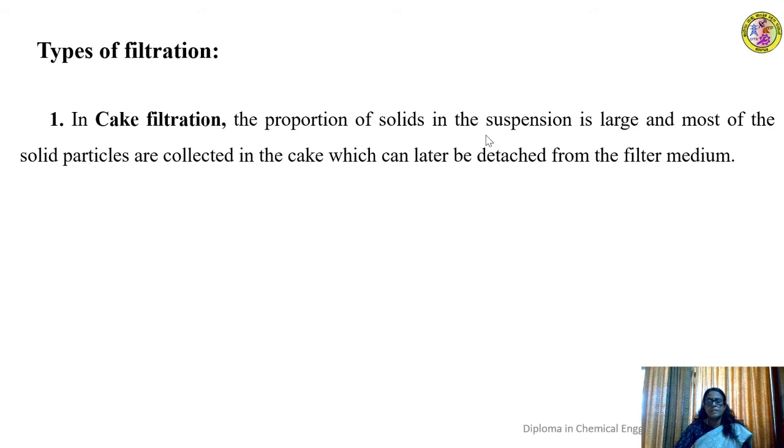The proportion of solids in the suspension is quite large, as I already told you. Most of the solid particles are collected in the cake, which can later be detached from the filter medium. The solids go on depositing on the filter medium during the filtration operation, and that deposition is called a cake.